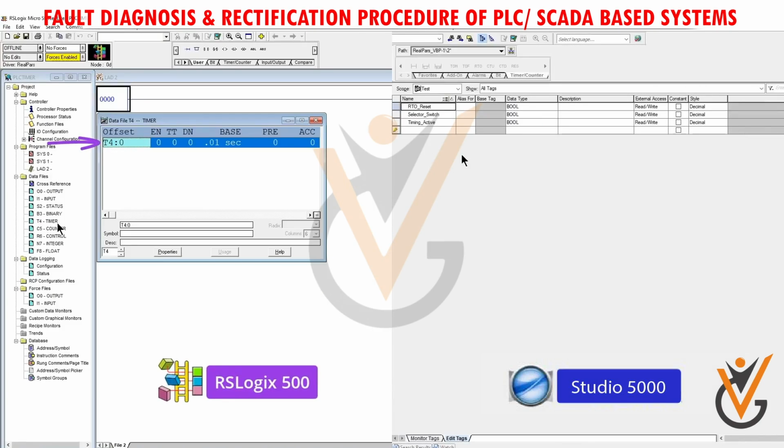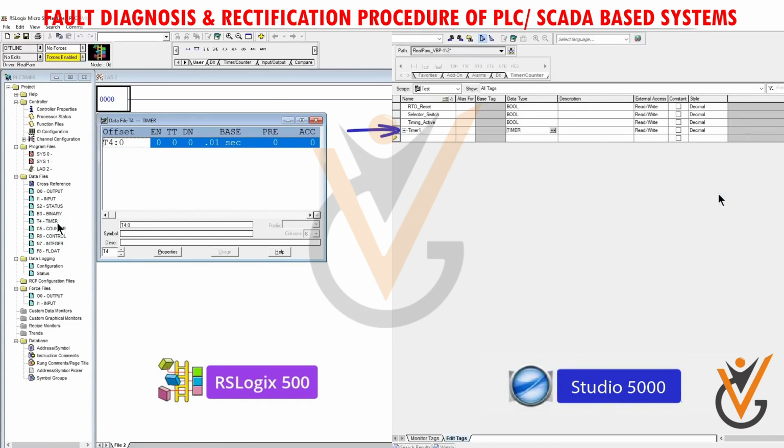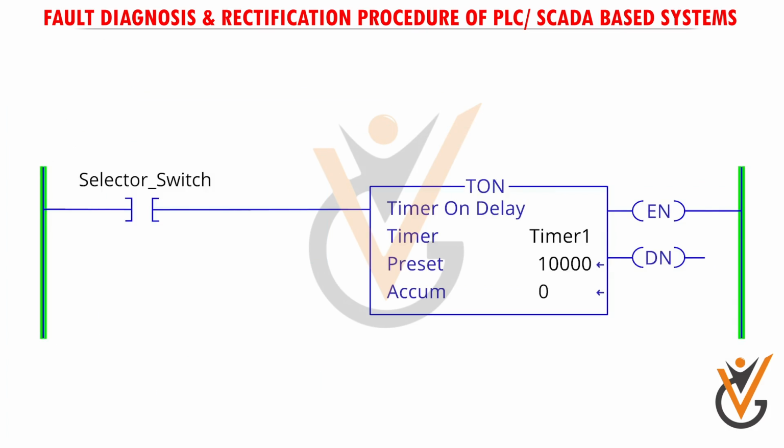Some PLCs create the timer file name for you, and other PLCs have you create the timer file name. For all of my timer examples, use the timer file name timer1. Also use a selector switch to enable and disable the timers.